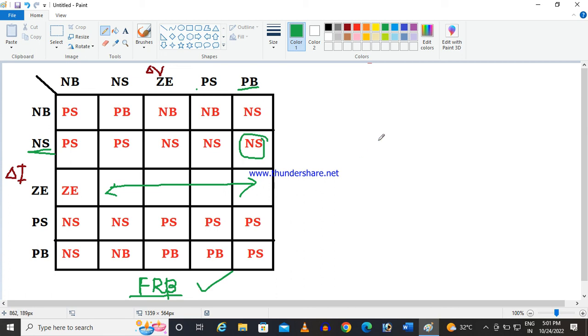Okay, and then you define your fuzzy system based on this truth table or this rule base. Then in each cycle the fuzzy system will defuzzify based on the rule base, and it will give the output physical quantity.